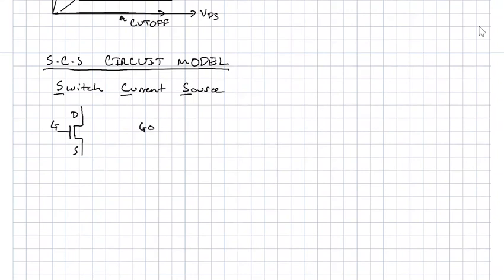So if we have our gate and we have the drain and source, the gate's really that control electrode. And I'm going to remind us here, no gate current, but we also have no drain source current flowing. And so this is our VGS less than VT. So we haven't turned the device on. So this is cut off. But then we can actually turn it on in saturation.